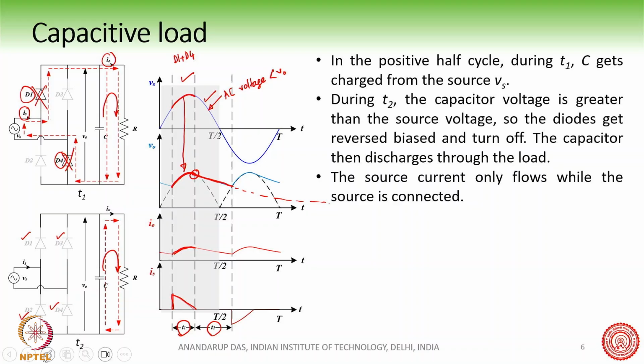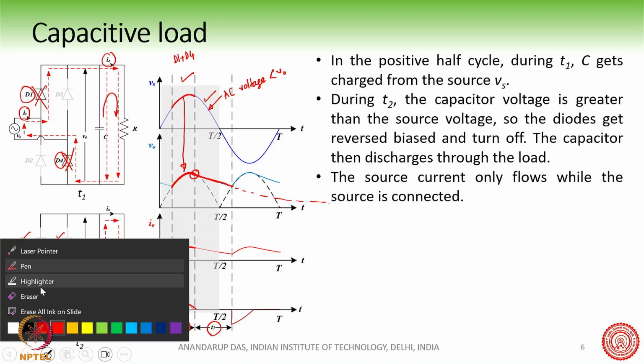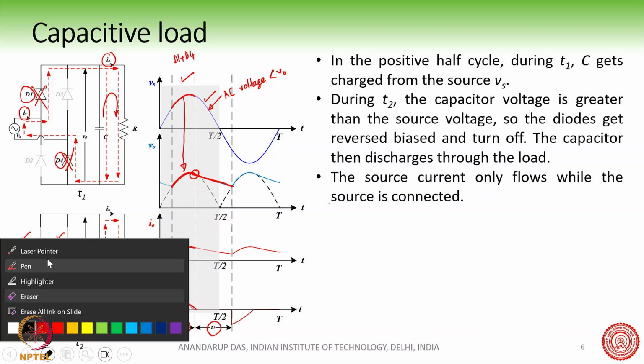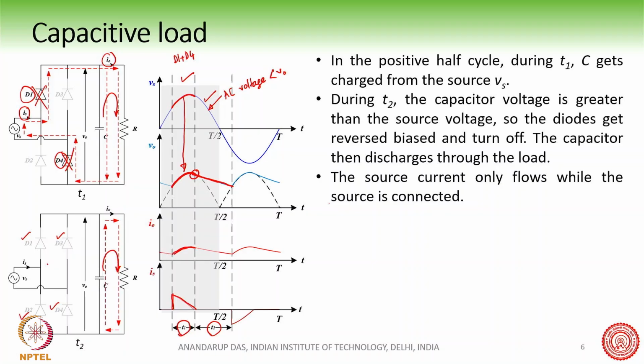If the RC time constant is very large, we can take a small part of it, and so we can see up to this point in the waveform. Of course, since all diodes have stopped conduction, we don't have any current flowing from the source during this point of time, and the I0 current is something like this. This will continue until the voltage again.